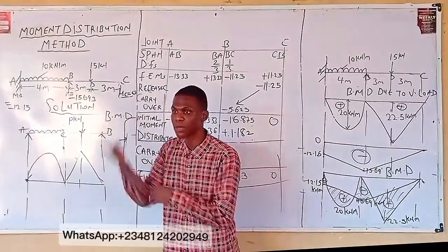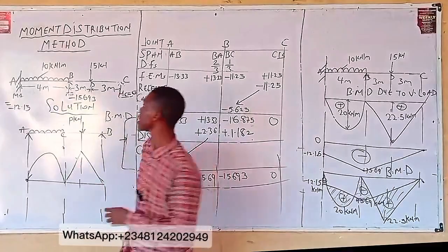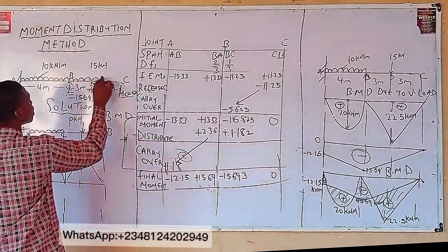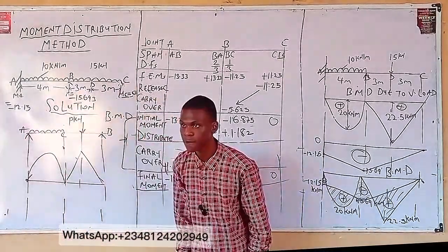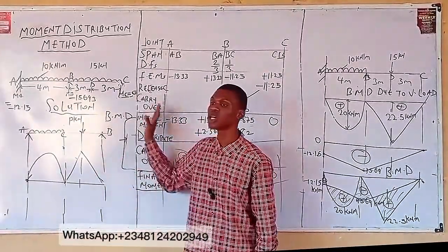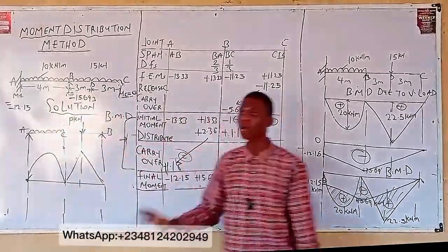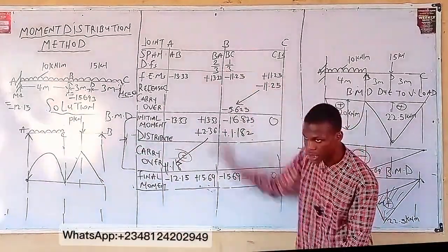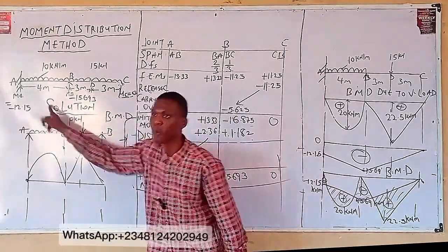Say you are given another beam of this type of support, loaded with another load. Let's say the load now, all through, is a UDL. When we just finish solving this new question, what is the difference? The loading is different. That's the difference between what we just solved and this question. So the way you computed the value of this table will not change, because the support is the same.